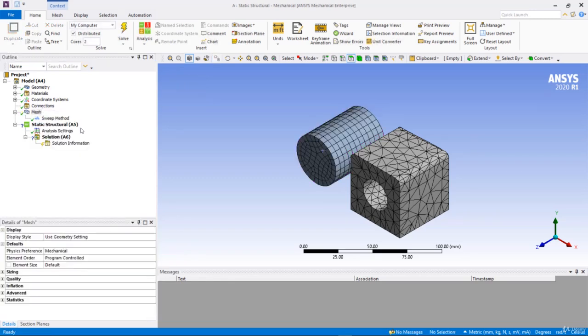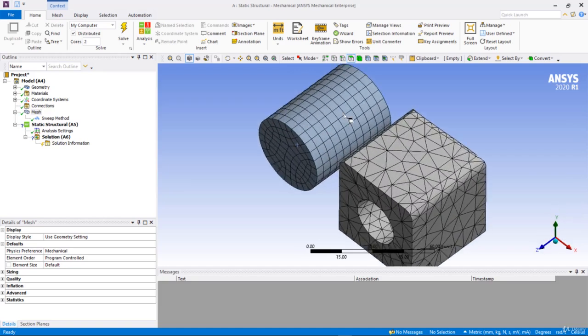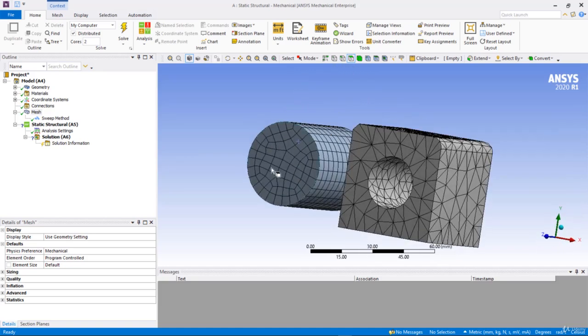So this is one method in which you can generate elements, and see here you are able to get hexahedral elements here and over here also. You can take refinements, and if you want a great structure, you can split these objects. As I already told you, generating hexahedral mesh requires a lot of manual operations and a lot of theoretical background, because with simple settings we can't generate hexahedral mesh. Tetrahedral mesh can be generated somewhat, very good mesh can be generated with tetrahedrons. That's not a problem even though we are using automatic meshing.